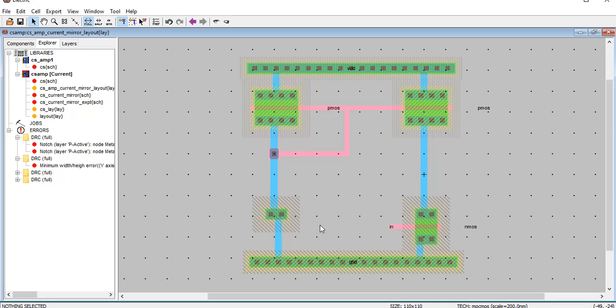And we are supposed to eliminate this because I do not require this portion, because only I require this PMOS. So, this is not required actually speaking. Oh, or else this is required, because this is where you connect both the wells. No, this is not required. So before eliminating, let me try to delete all these things, because I only require this one PMOS, and look at how exactly it is connected.